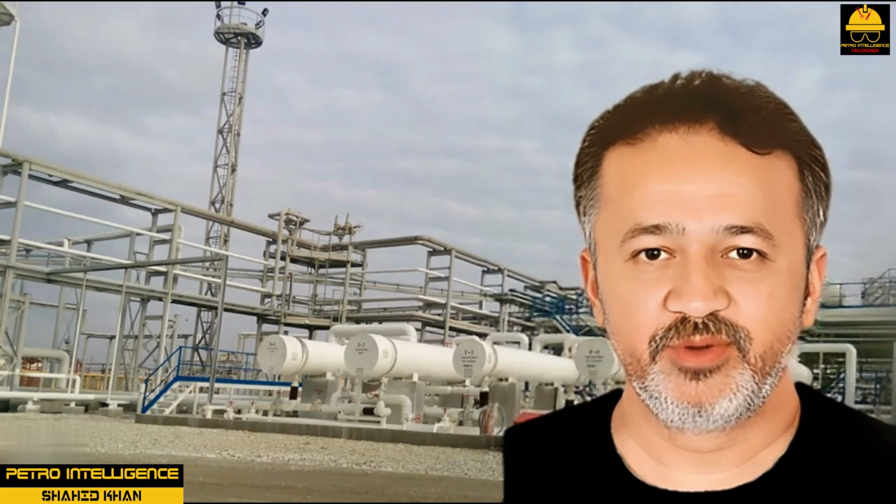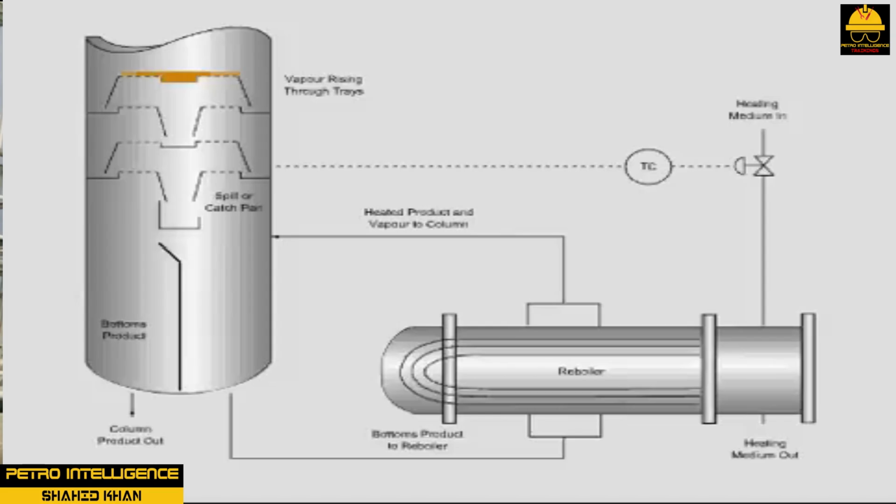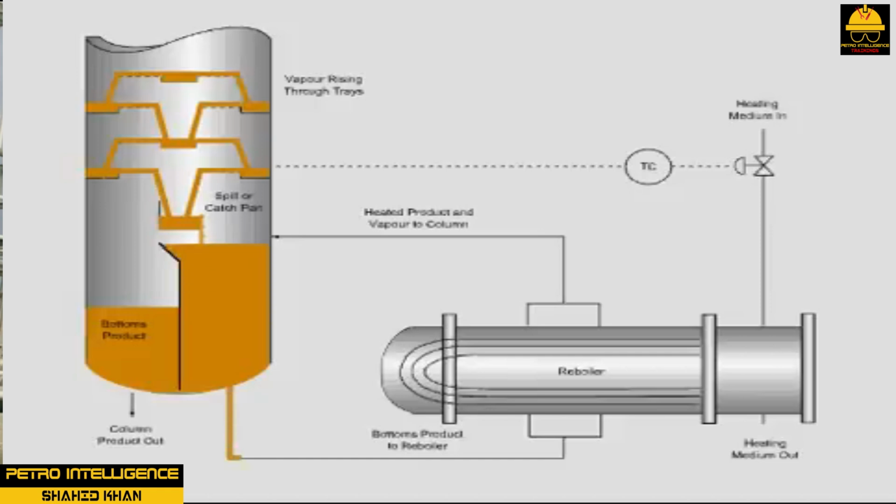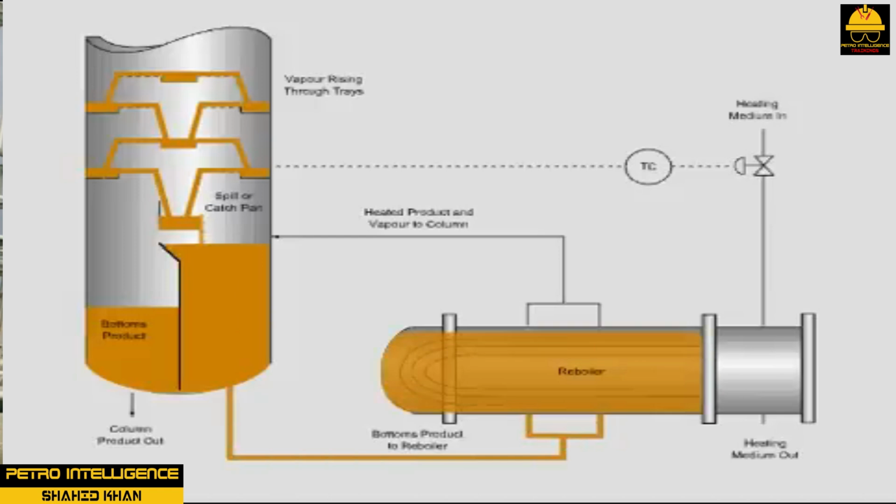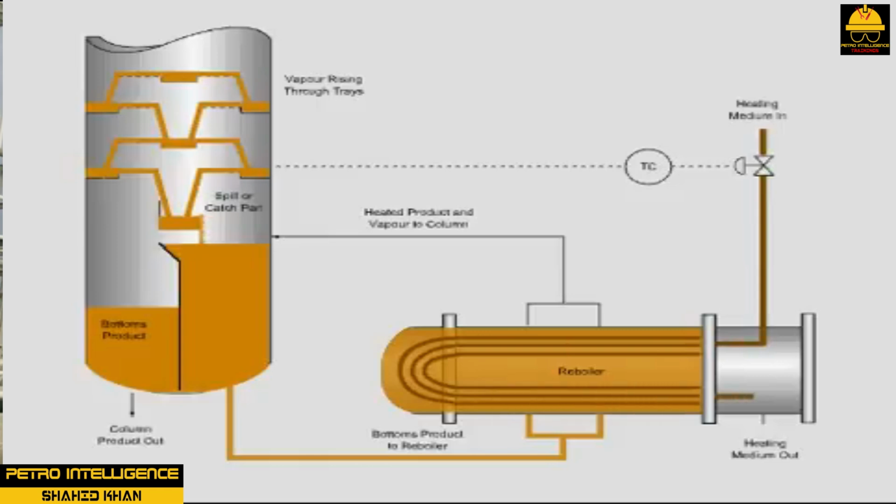Vertical and horizontal thermosiphon reboilers. A thermosiphon reboiler is a fixed-head, single-pass heat exchanger connected to the side of a distillation column. Thermosiphon heat exchangers can be mounted vertically or horizontally. The critical design factor is providing sufficient liquid head in the column to support vapor or liquid flowback to the column.